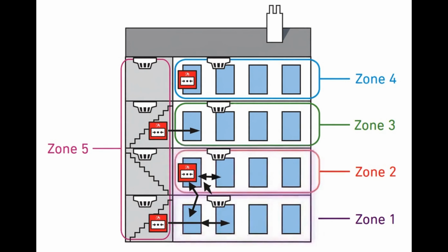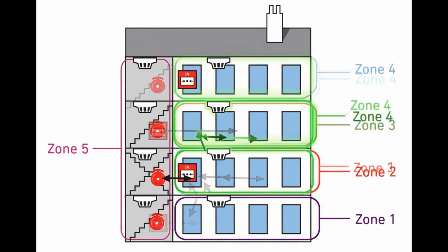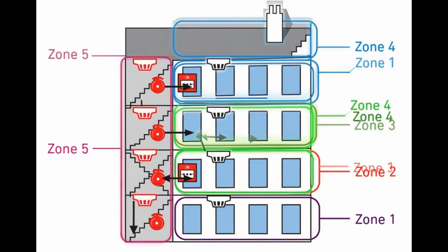Zoning organizes information for responders. Limit zones to one floor maximum, with no more than 20,000 square feet. Always designate stairwells as separate zones.